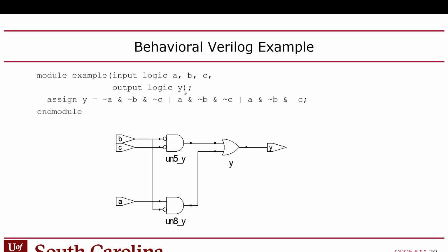Yes, I was coming to the same point, isn't that like an NP-hard problem? Yeah. So logic minimization is NP-hard, and so is the mapping process. So you have to minimize it, and then you have to map these to the actual gates on the FPGA. Then you have to place and route, which is also NP-hard. Those are all NP-hard problems. But in practice, the thing that takes the most time is the placing and routing part. This actually, usually in our experience, is pretty fast. It's not guaranteed to be optimized output, but we believe it anyway. Right, exactly, yep.